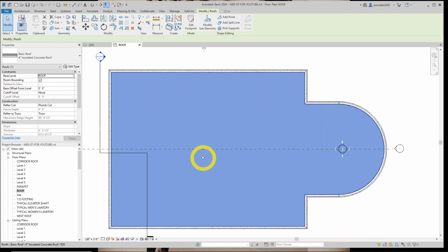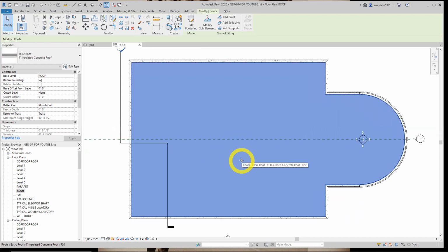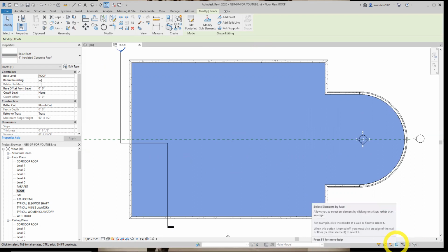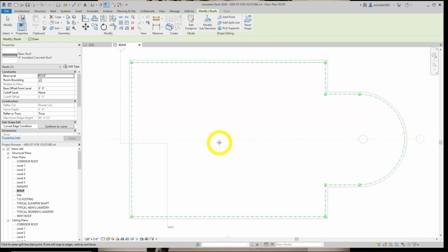So we're still in the roof floor plan. We have the roof still selected. If you unselected it, we have to redo that. I just kept it going. And we're going to try the add, and I showed you this function down here, which it's talking about in the book now in 328, but I did it a little ahead of that. We're going to do add split line. So we're going to add our first split line as shown in figure 7.8 on 329.